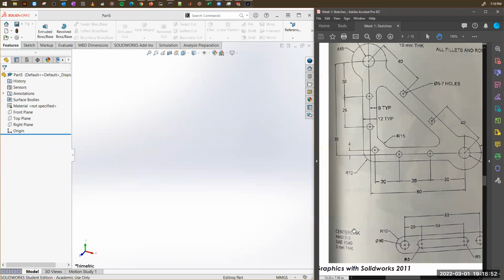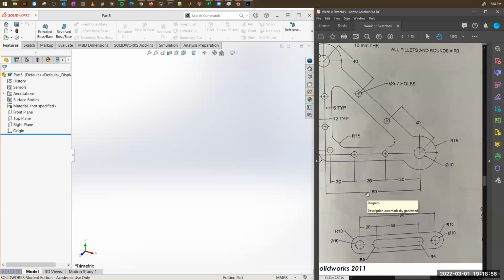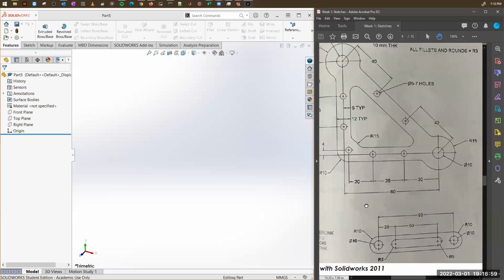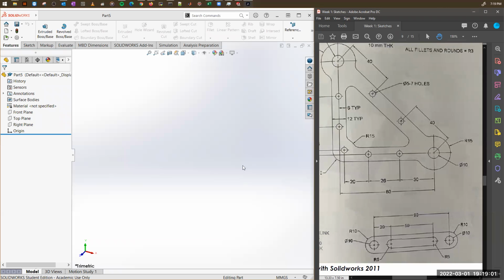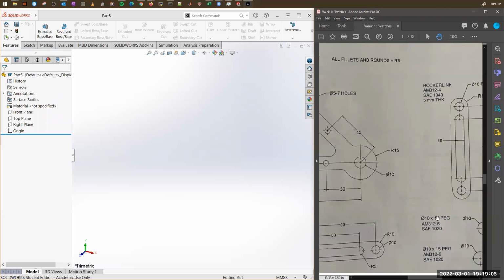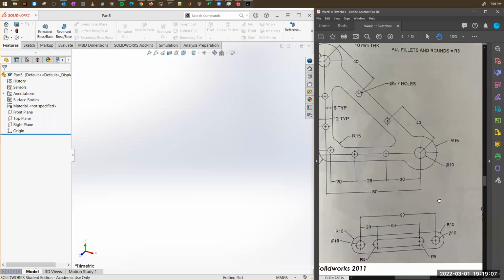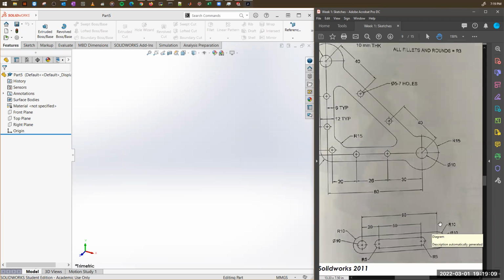Sometimes it's a good idea, if the names are different, or if you think the specifications might change later on, to save it as a different name, so that it's not gonna modify anything other than the ones you're working on. It might happen that you're changing a specification, and SolidWorks usually links everything in the assembly. You might be messing up something. It's better to be safe.